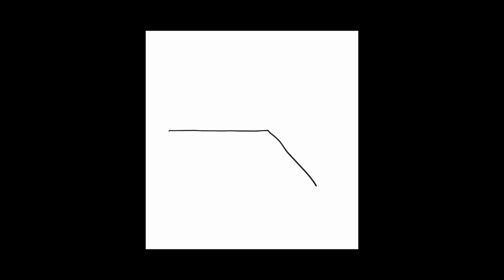So here I'm giving you a reference line and I'm going to give you a weld symbol. Go ahead and pause the video here and see if you can figure out what type of weld this symbol is describing. If you said fillet weld, then you're correct. The symbol for a fillet weld resembles a right triangle, or a triangle with two sides that are perpendicular that when they meet form a right angle, or a 90-degree angle.